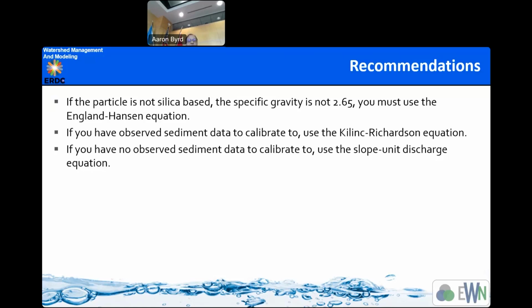We got really good results from the Richardson equation, but there is always something for that good result. That is, we calibrated it, but the calibrated values then translated to the validation pretty well, right? So we recommend this as one of the really good equations, provided that it's empirical based and it needs calibration. If you have no observed sediment data, like I said before, for ungauged basins, and you don't have any parametric values to input, use the laboratory derived equations.